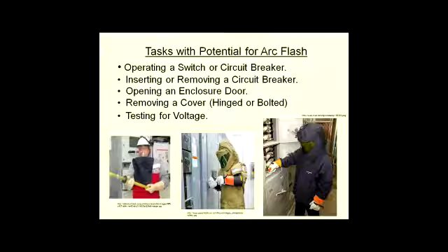Inserting or removing a circuit breaker, changing a fuse. We're not talking about that little fuse, although all precautions should be taken when you're changing a fuse in your electrical panel, or flipping a circuit breaker, depending on what kind of panel that is. But we're talking about the bigger ones, right? When you're removing that circuit breaker, or putting one in, you're making a contact. All of a sudden, the electricity is going to start flowing, so that can cause an arc flash.